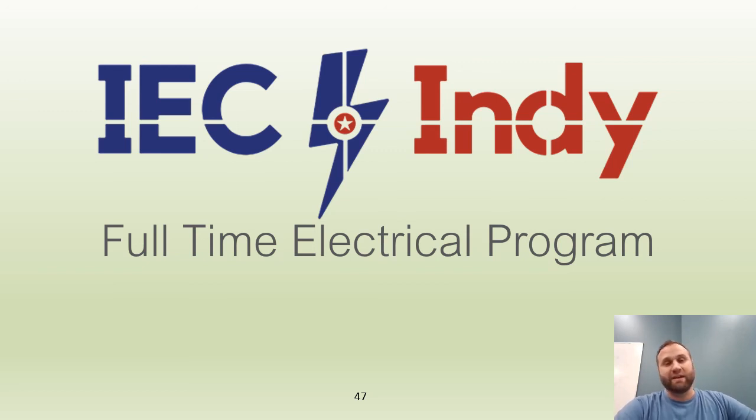That being said, I'm a huge advocate for, as technology is changing, that we not downsize or reduce the size of our neutral conductors in the future, as we're seeing more and more nonlinear loads on the neutral, even in residences, as we include more and more fluorescent lights and LED lights. We're looking at more computer chargers, smart devices, computer terminals, smart TVs, smart refrigerators, you name it.